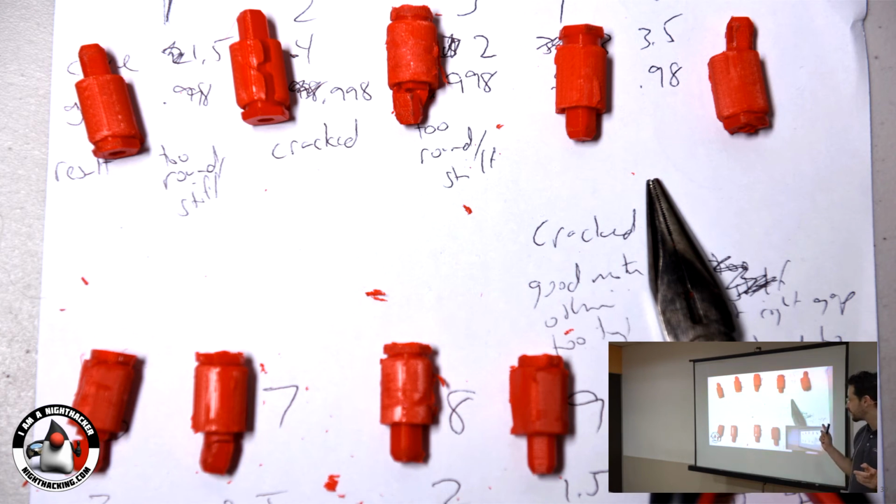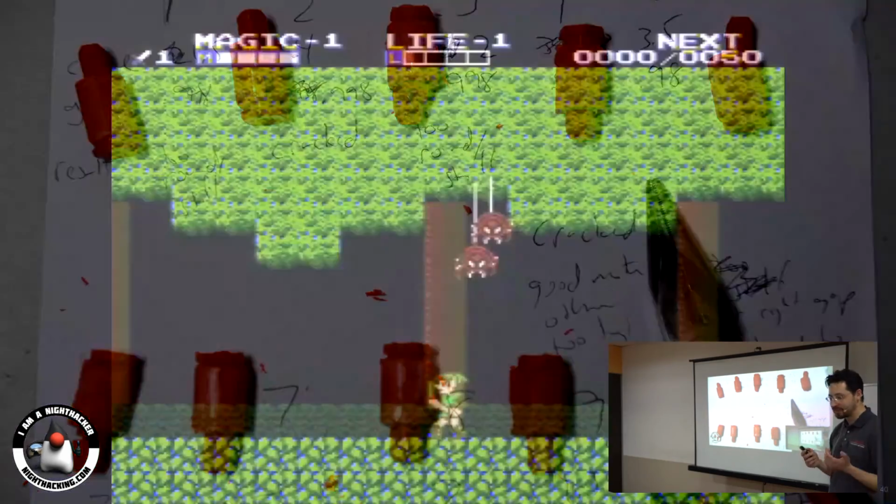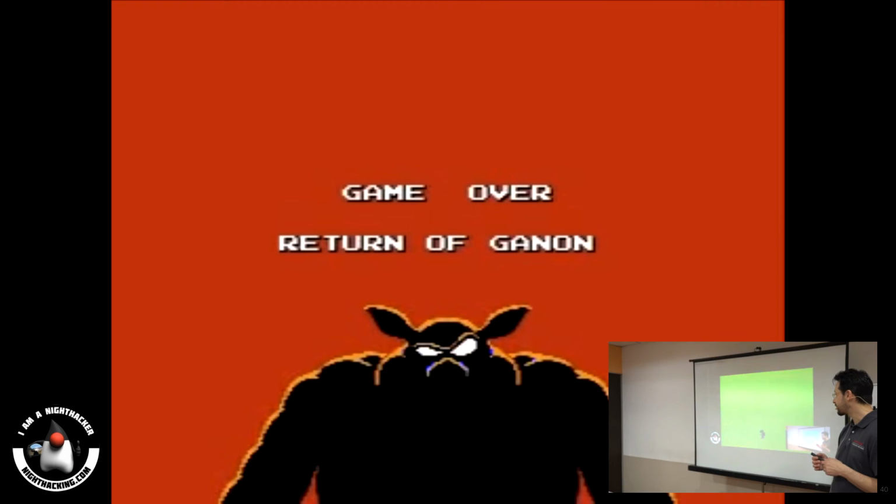My initial design for the hinge was to use a polyhedron, like a 20-sided polyhedron, and that way it would snap at fixed positions. But when you use sharp edges like that and you open and close it, it takes about 50 times and it's perfectly smooth, like you printed a circle. So that doesn't work very well, sharp edges. So it's quite a hard challenge to do a design like this.